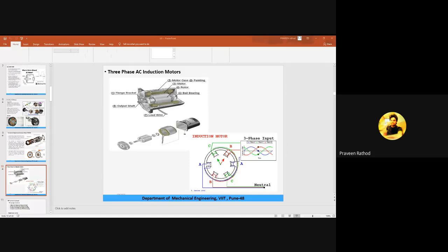It is simple. Electric motors have torque speed characteristics close to the ideal performance of a vehicle traction power plant, and are able to provide near the maximum power over a wide range of speeds. So we are going to use this type of single electric machine with a final drive. There is a maximum torque at lower speed when we use an electric motor.